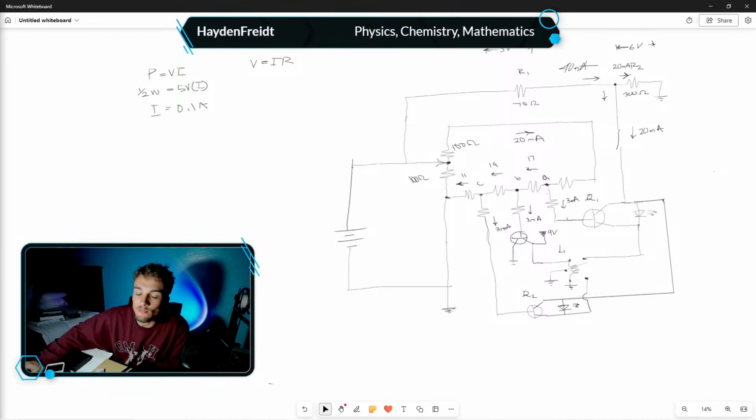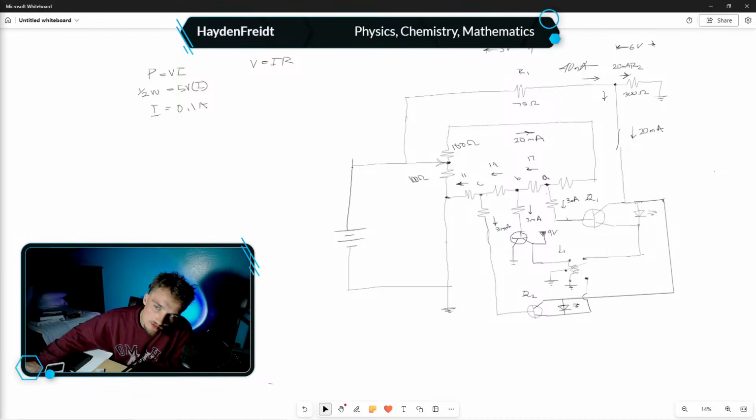The potentiometer has a maximum current of 100 milliamps. The power rating of a P101 potentiometer is 0.5 watts, and the potentiometer has a maximum current of 100 milliamps. I guess that makes sense. I'm pushing 90 milliamps, but I'm not even close to 0.5 watts, and it's getting really hot.